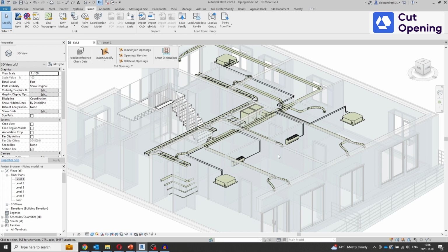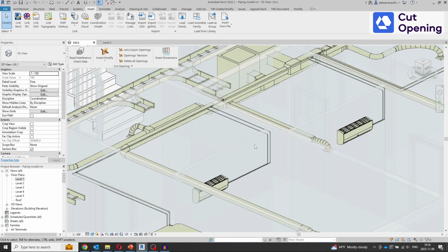We'll do the insertion of openings in 3 stages by the order the models were opened. Also, since the architectural model is linked, currently we will be inserting the opening placeholders that, spoiler alert, can later be inserted into the architectural file as the real void openings. Let's start with the pipe openings.